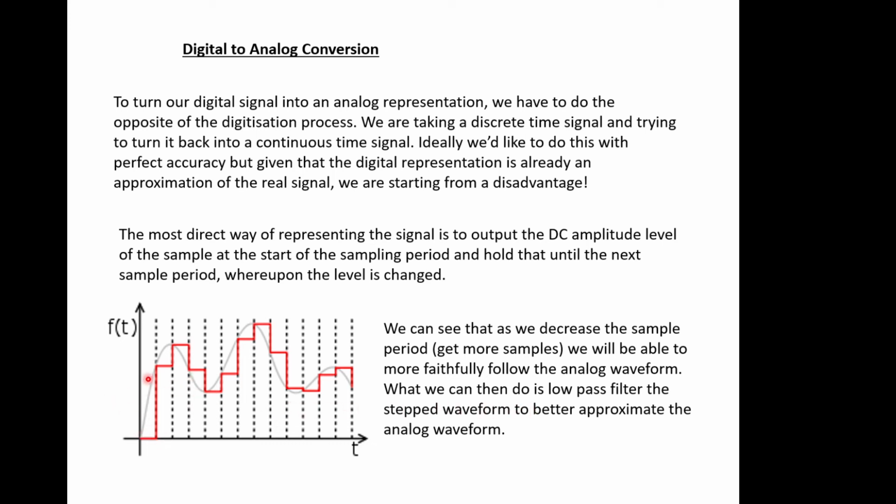But even if we've just got this choppy function here, what we can actually do to that is low pass filter it with an analog filter, which we now know all about, and that will track the average of this response and will give us a good representation of the output that we want. And the question just becomes, how accurate is that going to be?